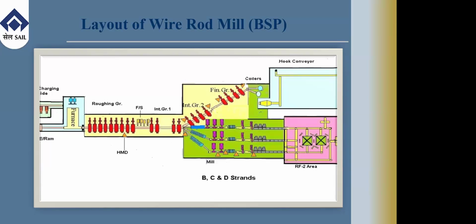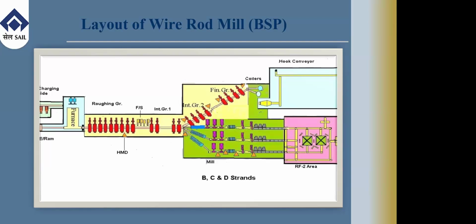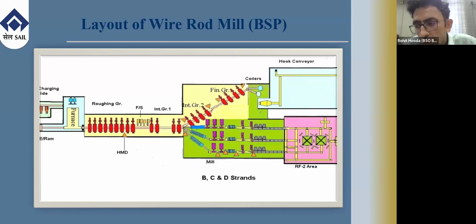It will improve the surface finish of the wire rods, because the final rolling of wire rods and TMT coils is done through rings, not through rolls. So we have procured one machine which will grind these rings through CNC technology. It will help us produce wire rods and TMT coils with better surface finish and better tolerance also.